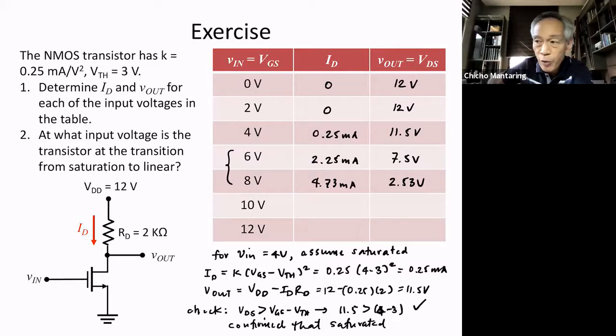Yeah, going back to that question about IC approximately equal to IE. I guess in real life, the error that it might introduce might already be within the tolerance of the transistor. That's why the rule of thumb of designers, usually when beta is high, is to just make IC and IE equal. Because the parameters of the transistor are not really exact anyway. So that's why that assumption is also used quite a lot.